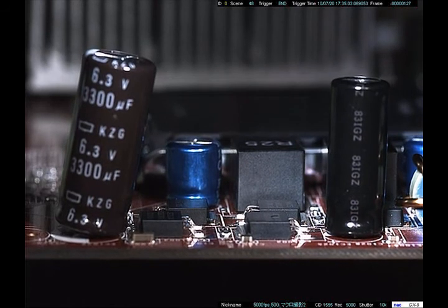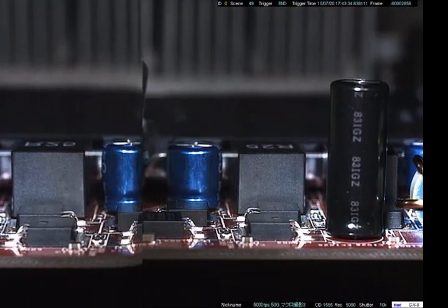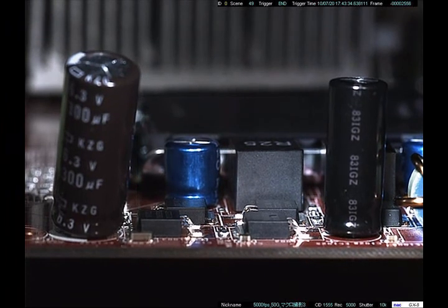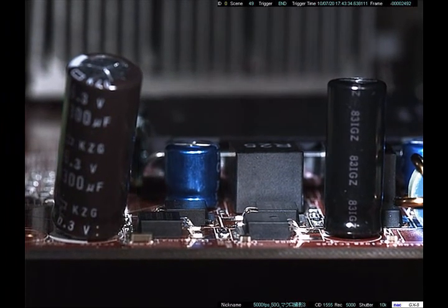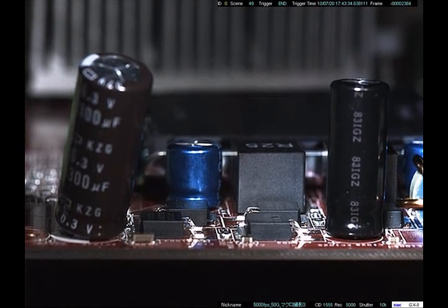With every component, board, subassembly, and assembly responding at their own resonant frequencies in all three axes, as well as the rotations around those axes, simultaneously, any mechanical defect or weakness in the device will be forced to rapidly fail.